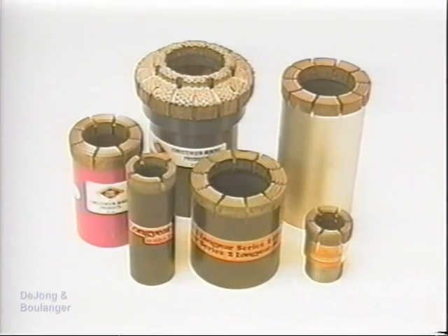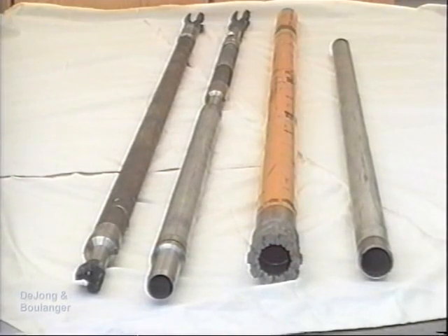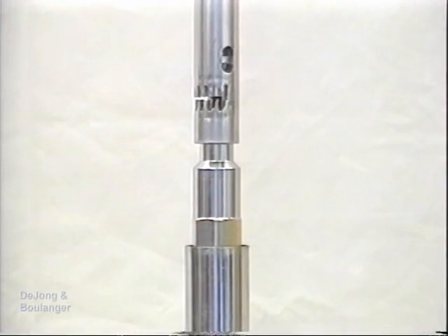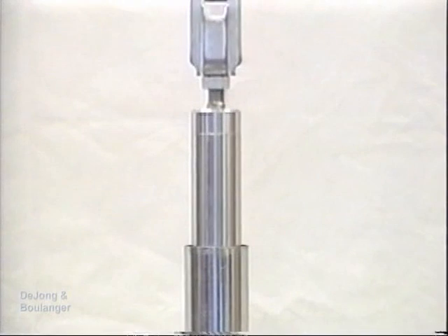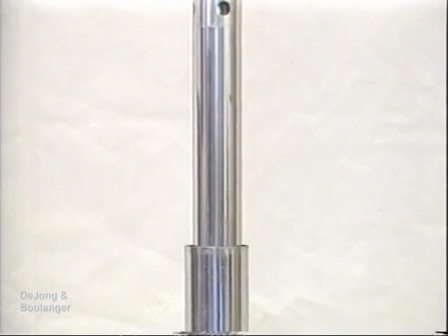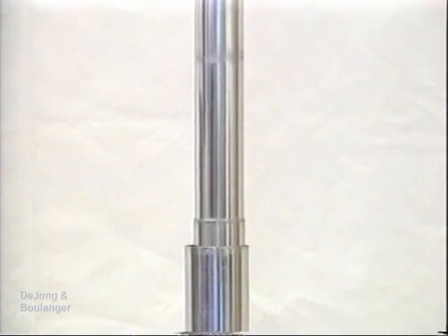Diamond bits are the most versatile since they can produce high-quality cores in materials ranging from hard or very dense soil to hard rock. As shown, coring bits come in a variety of shapes and sizes, each of which is suited for a specific situation. Some systems, such as the Christensen 94 pictured here, can perform multiple tasks such as drilling, coring, and sampling. Wireline retrieval systems expedite coring by removing only the full inner barrel from the hole, thus retrieving the sample while leaving the outer barrel and drill rods down the hole.